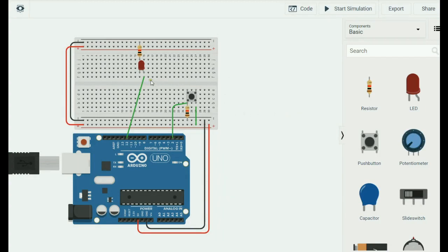And this one has an LED again. It is connected in a little bit different way over here on this board. And now I also have a switch. So I have also input as opposed to just output. But let me go over this and explain it first. So pin number 12, digital pin 12, is connected to one side of the LED. It's this side, the one that's kind of slanted, as you see, is called the anode. The other one, the straight one, is the cathode.